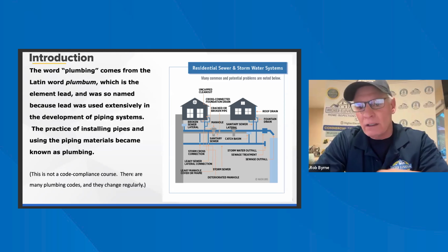Drain valves. There's a way you can drain the sediment from the tank. It's helpful with getting all that debris from the bottom. It allows you to flush out sediment and debris from the bottom of the water heater. Location on these drains are normally towards the bottom. Obviously, that's where the sediment's going to build up.